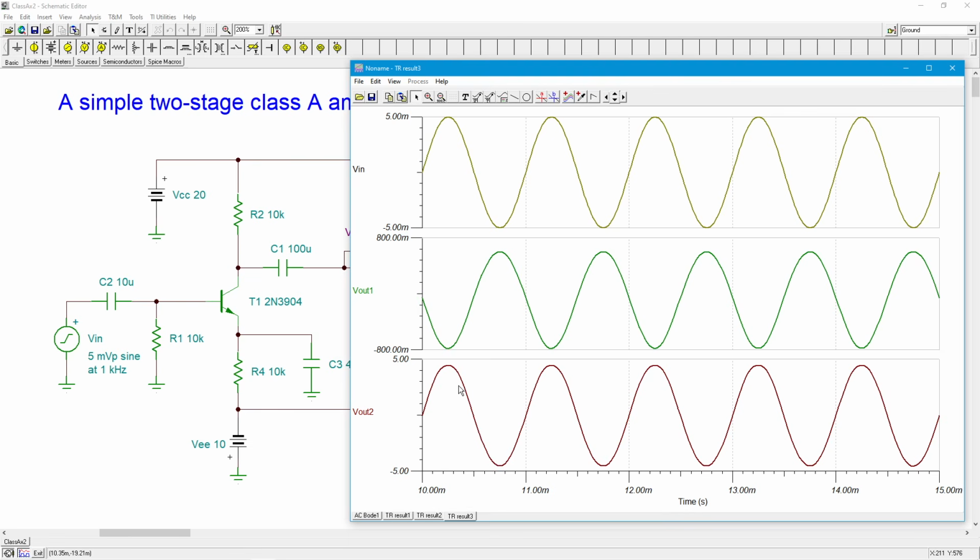Not perfectly, right? I mean, there's other distortion in here, but that's why the second harmonic, because the second harmonic is like the biggie when it comes to creating this kind of distortion in this waveform. That's why the second harmonic is so small, comparatively speaking, right? I mean, it was like 3% for the second harmonic in V out number 1, right, for this stage. And it was less than 1% in V out number 2. Because V out number 2 is producing this mirror image. It's unbending the bent wave. The part that was pointy gets squished, and the part that was squished gets pointy.